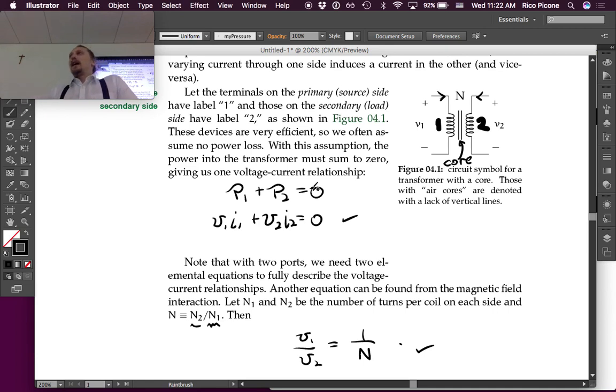But when it gets to your house, that's not the voltage you want. You want it to be lower. So then you transform it down to a higher current, lower voltage form of the signal. You lose a little bit, but you lose less than if you had transmitted it at the lower voltage and the higher current. So that's the idea with the transformers that you've seen.